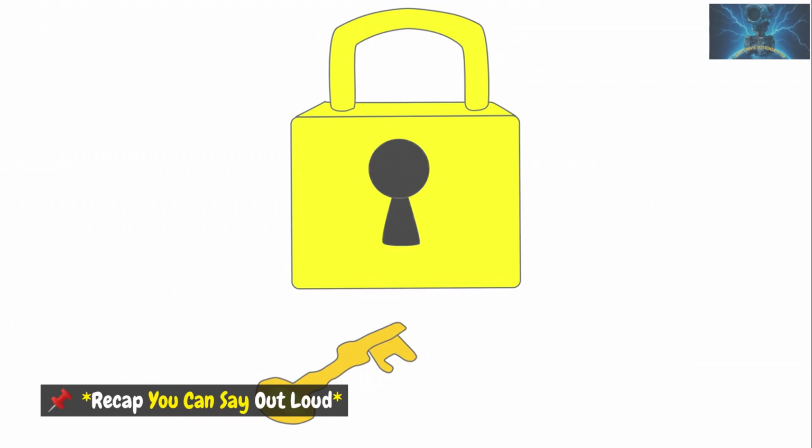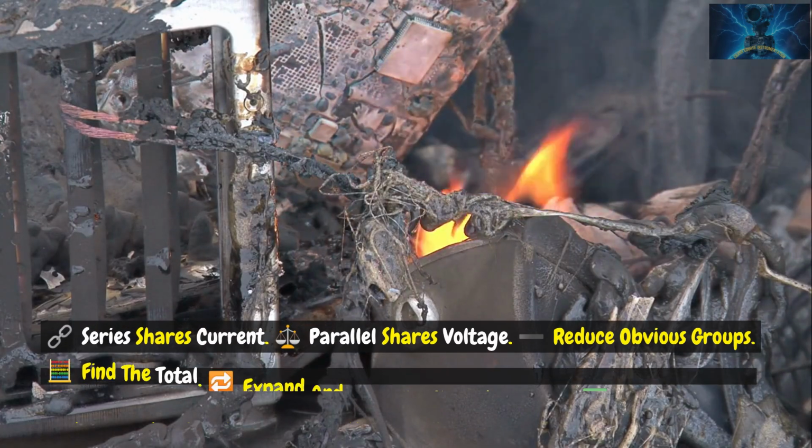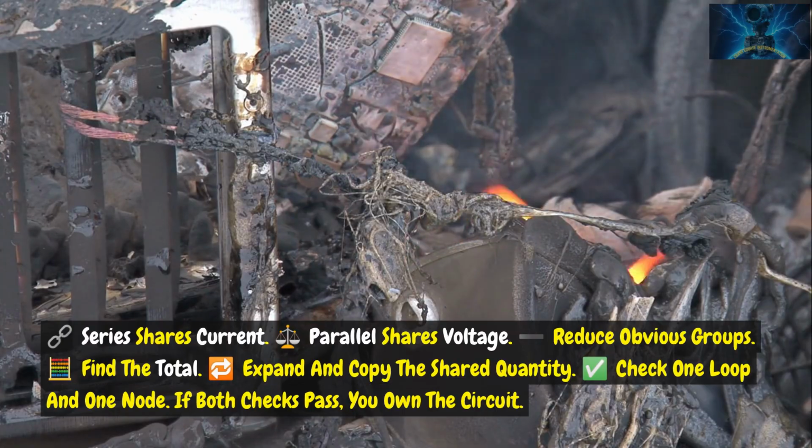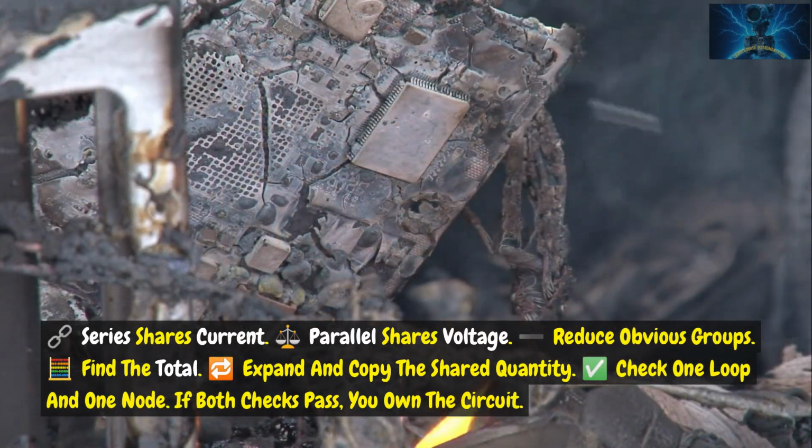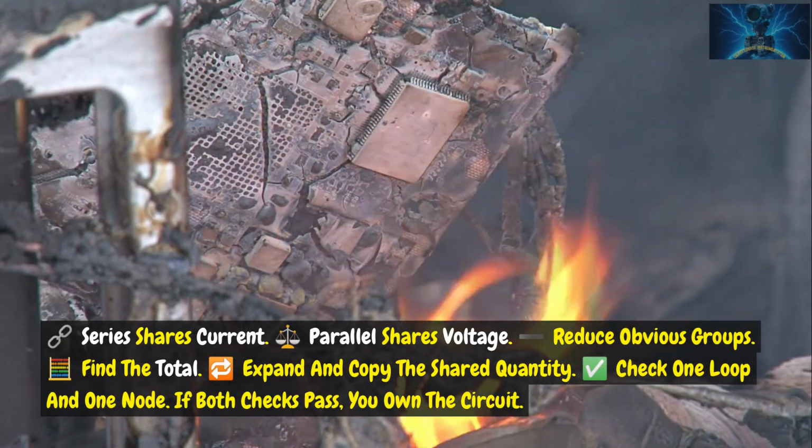Recap you can say out loud. Series shares current. Parallel shares voltage. Reduce obvious groups. Find the total. Expand and copy the shared quantity. Check one loop and one node. If both checks pass, you own the circuit.